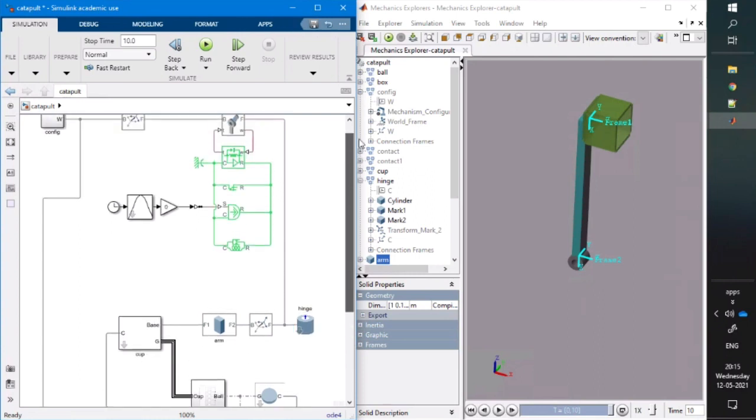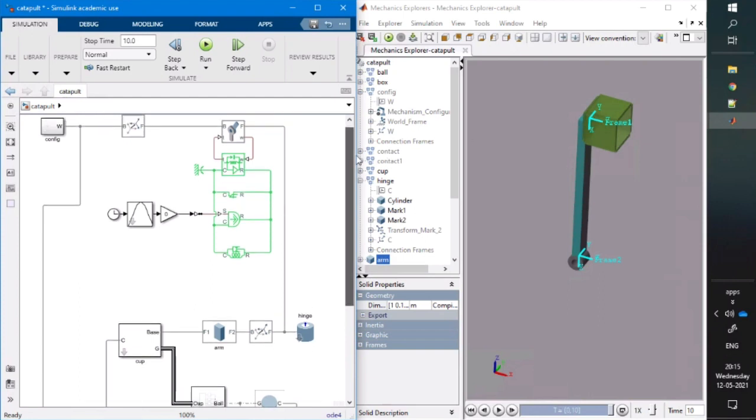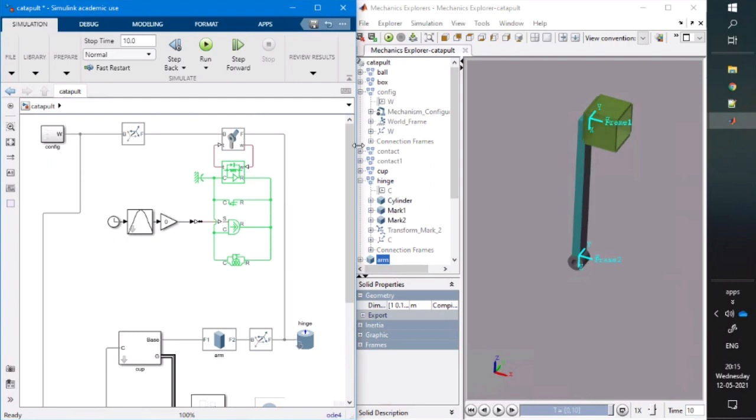And to tune these variables or the parameters, the stiffness, damping, and so on, you could use one of such apps, maybe response optimization, to check how much is the damping, in how much time it settles, or how much the rebound force that you can have. So all those things that you can tune automatically. Again, manually you can try, but if you want to be on more on a cooler side, you can use the built-in apps.